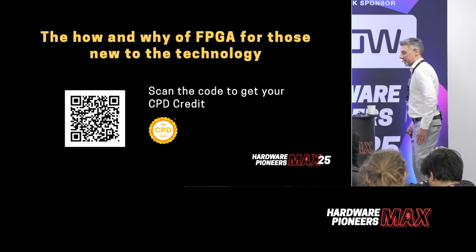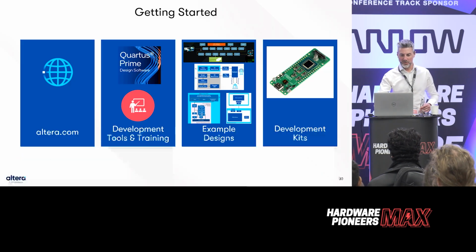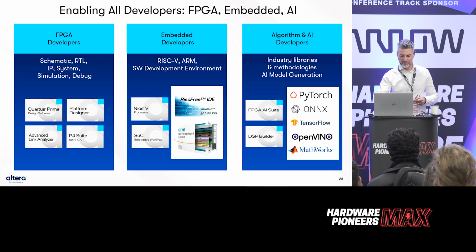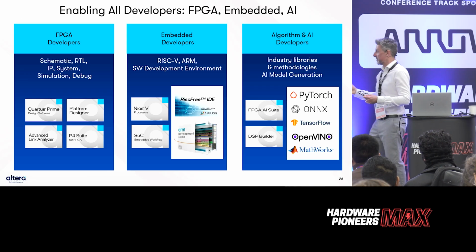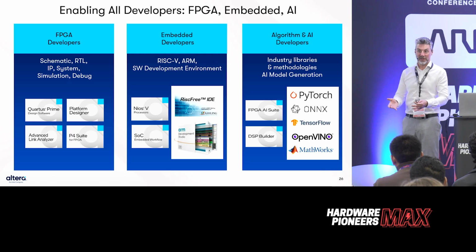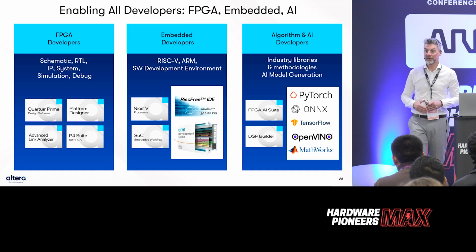Yeah, so I didn't cover that. Yes, so we do. Let's go back. A few of us talked about it yesterday. We do a C to gates flow basically called oneAPI. So basically you can write your code in C, C++, and it will generate RTL for you. It will generate a bit of Verilog or VHDL for you, but it's like a black box effectively. Is it free to get that software? Yeah, it's part of the tool. Yeah, absolutely. Okay, great.